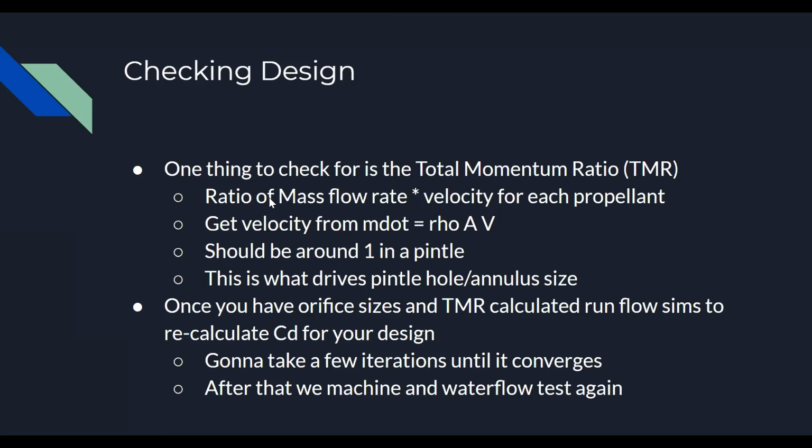Pressure drop is directly related to the velocity through an orifice, so generally this is driven by pressure drop. I would say don't worry about that as long as your total momentum ratio is around 1, like between 0.9 and 1.1.